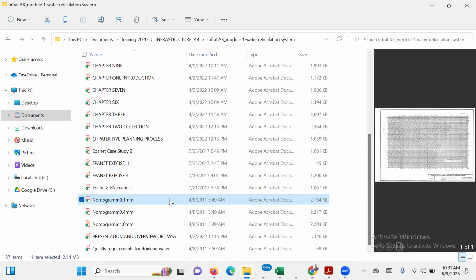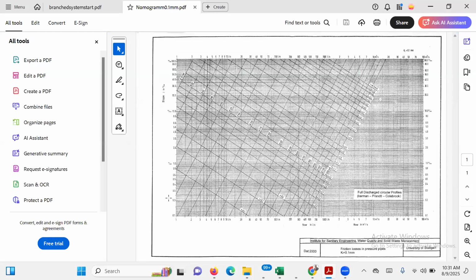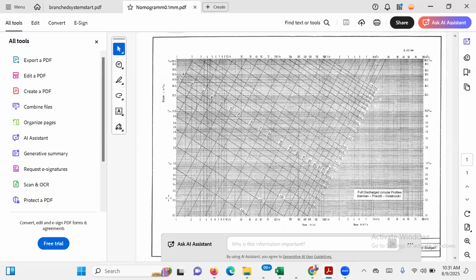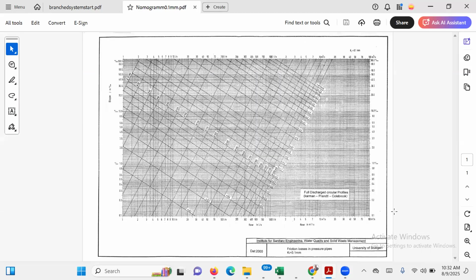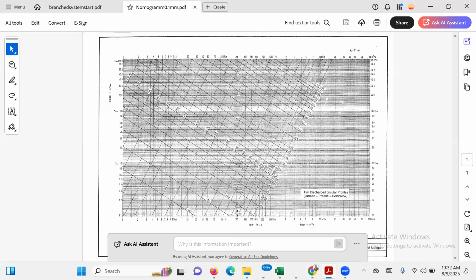And then last week also, we talked about nominal value. Remember? Once I get the Q, the quantity of flow, I'll read from my table, and I'll know exactly the type of pipe that I need. But here, if you want to be more precise, more accurate, then you might consider using this chart, where the horizontal is the flow and the vertical is the slope. So with the slope of the ground and the flow required, I can easily get my pipe size.